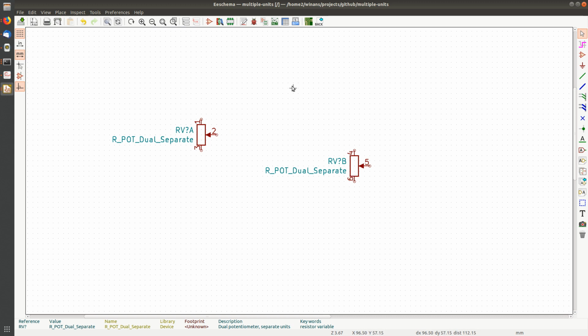The FPGA is not designed that way. It would be completely inappropriate to swap, as you recall, the D unit that was over here, like the power interface, with the A unit that was up here, which was a bunch of I/O pins. They're physically not the same. The pins are in different places and completely different roles. They have nothing to do with each other, other than the fact that they're on the same physical device. These 2, on the other hand, are exactly the same.